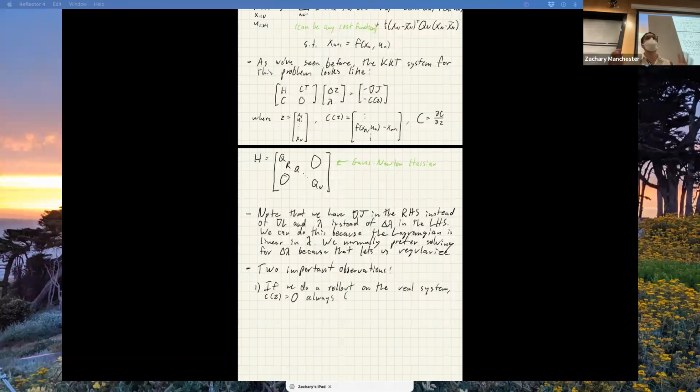That's assuming the true dynamics. That might not be true for my approximate, crappy dynamics model, but on the true dynamics, that's going to be the case. So I'm going to set that equal to 0 here, given a real dynamically feasible trajectory from the real system. Those are the dynamics constraints, saying x_{k+1} equals f of x_k, u_k. If I simulated this on the real system, that's true by construction, like what my Runge-Kutta method is giving me. So that whole vector is going to be 0. Those are the dynamics errors.